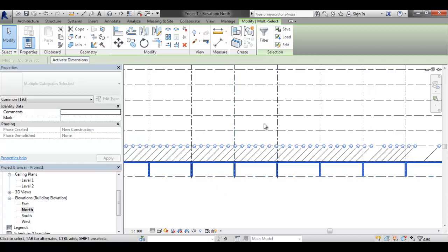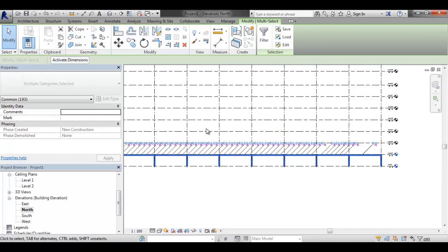And then I'm going to type UP for unpin. So now I've unpinned those elements. So those were pinned to specific items in geometry. That pinning deals with the beam system. That beam system, now I should be able to move my beams within that. And so they're not evenly spaced. I can have abnormally spaced in case I need to put a hole in the floor or anything like that.